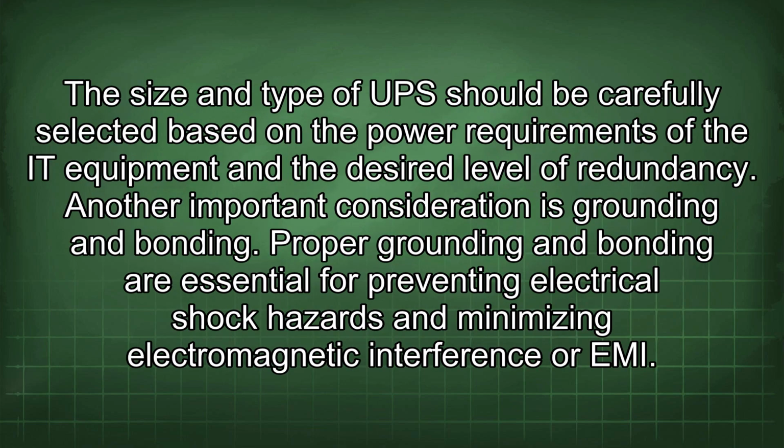The size and type of UPS should be carefully selected based on the power requirements of the IT equipment and the desired level of redundancy. Another important consideration is grounding and bonding. Proper grounding and bonding are essential for preventing electrical shock hazards and minimizing electromagnetic interference, or EMI.